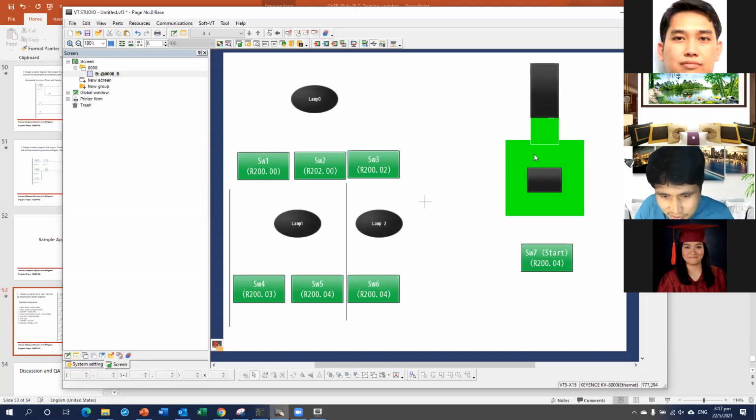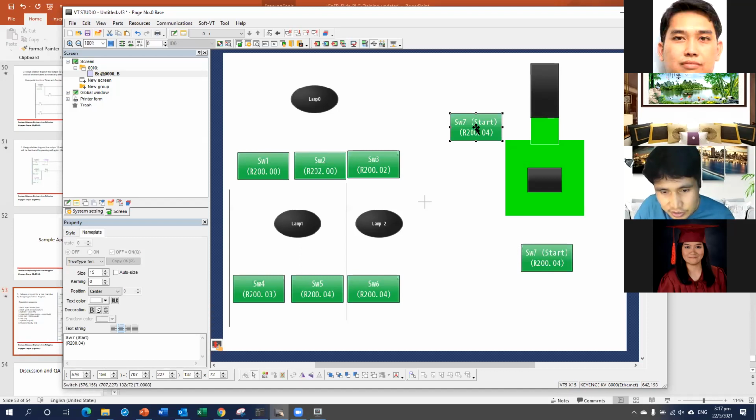And then we have a sensor. So Control C, Control V. Remember, maybe our sensor is a photoelectric sensor that detects the parts presence, whether you have a part or not, no part. So it will be switch 8. And then work detect. Okay.